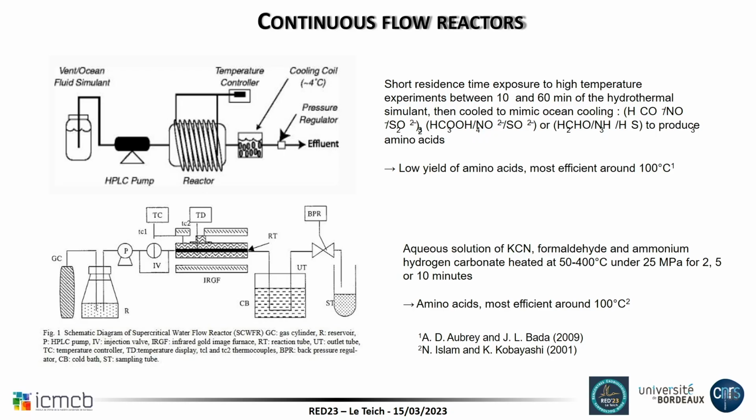So that's why people started doing flow chemistry. A flow reactor is simple. It's a pump. You pump a liquid, so it could be a fluid that is loaded with different kinds of things, sulfate and so on. And it flows through a heater, a tubular reactor that is heated. Then you cool it down, you recover your sample, you analyze.